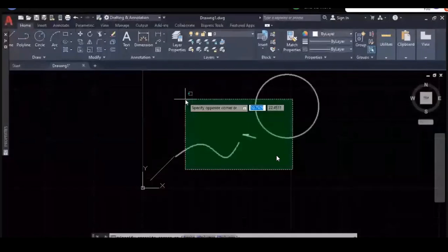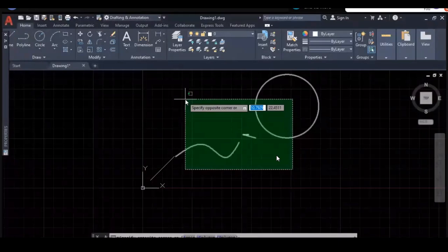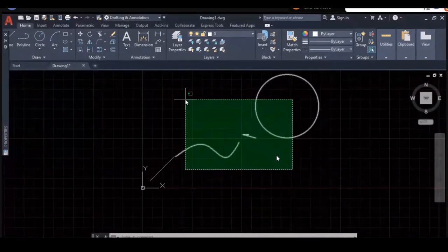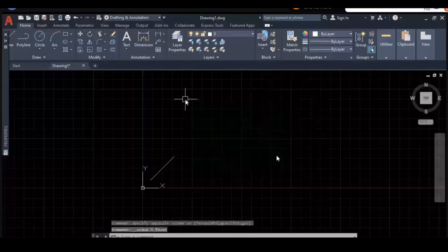It will show you in the green color. You can change that color as I told you in the last class. You can go to the settings, selection, color change. You can change it to any color. By default, it is green color. Click, delete. That's called selection mode. Rectangular selection. Even you can select by using the polygon method.